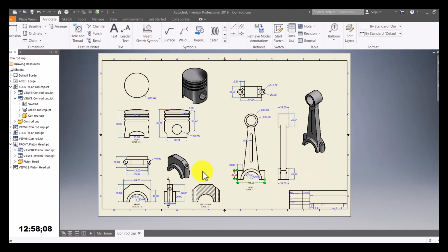Okay, now I've been able to bring out my dimensions. I've been able to bring out my dimensions successfully, and that looks good. So the next thing I would like to do is add my text. So to add text, I will just click on under annotate. You can see text. I'll click on text. Then I'll be able to label my three different parts.